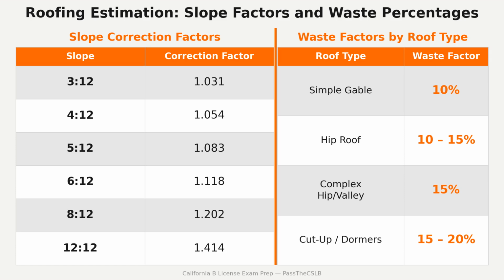At the eave, the drip edge goes under the felt. At the rake, the drip edge goes over the felt. Eave under, rake over. Four words. Adjacent sections overlap a minimum of 2 inches. Fasteners, maximum 12 inches on center.